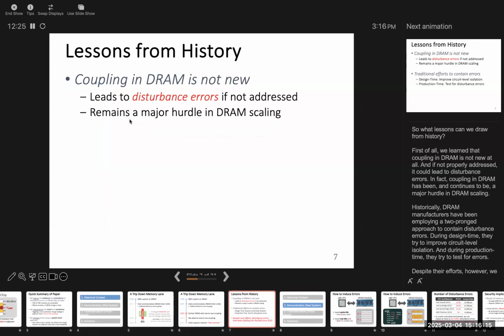I cannot go into that side because that is not my area, but it talks about disturbance occurring because of some electromagnetic effects. The way the current flows through the devices, it can induce electric and magnetic fields. If it is going through one particular channel of the transistor, it can affect, for example, the capacitor connected on the output, or it can affect the other connecting wires in the same chip which connect the other transistors.